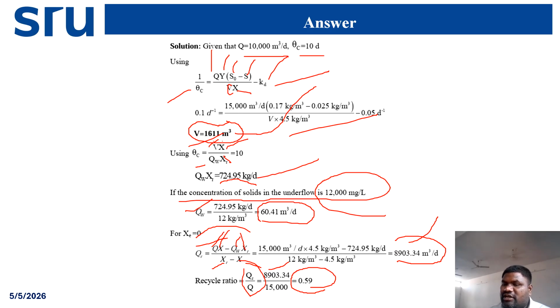Next will be the secondary clarifier. Here the sludge will be settled. Some portion of the sludge needs to be introduced back into the aeration tank. The reason behind this is that we need to maintain the ratio between microorganisms and the organic matter. Then only BOD removal will happen.